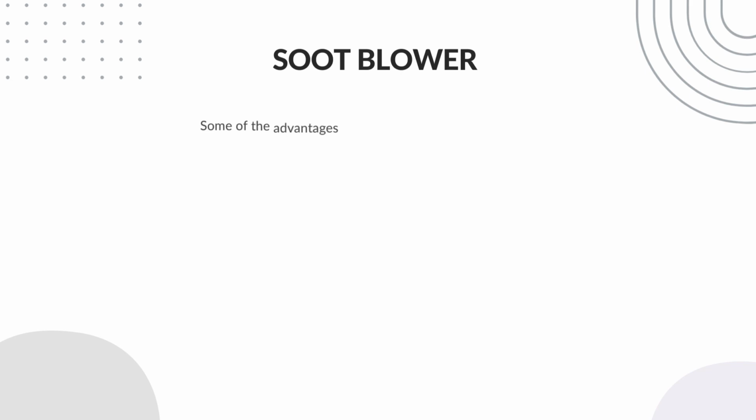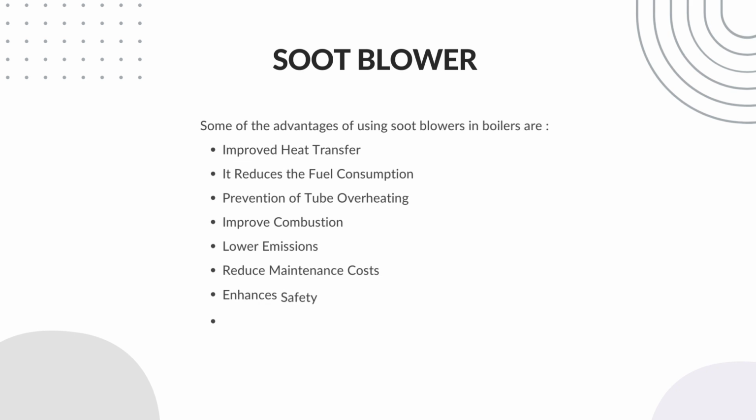There are several advantages of soot blowers in terms of boiler performance, efficiency and maintenance. Some of the advantages of using soot blowers in boilers are: improved heat transfer. Soot and ash deposits act as an insulating layer, reducing the heat transfer efficiency in the boiler.